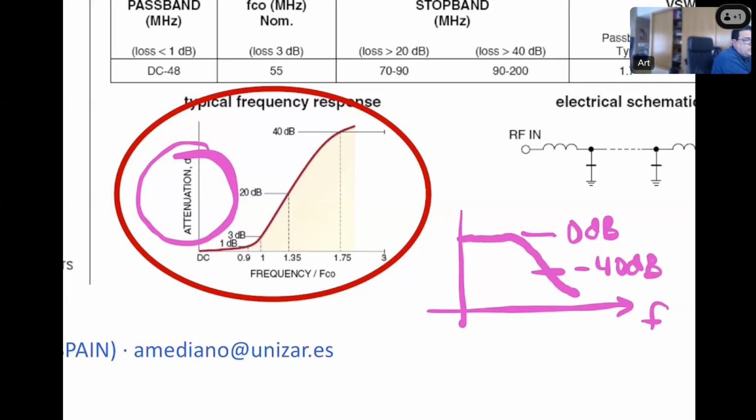In the same way, we are removing the losses and the frequency response of this network. If you are introducing in this path some kind of attenuator, amplifier, or something like that, you will be able to normalize, to calibrate, including the losses or the gain of the element you are introducing in the path of your signal. So now that you see how the instrument is, let's switch to this camera where we see the end of the cables.